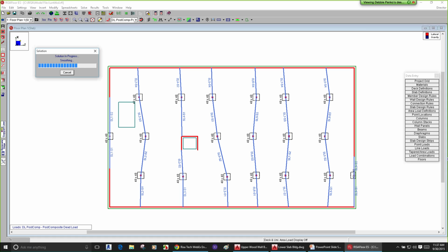Formwork, things like that, whether that makes sense to you. Maybe you just bump it to a 14.5-inch slab. Maybe that would help you because we were pretty close on punching shear. And then maybe go column by column, adding shear caps where you need them explicitly as you increase the slab thickness. But a lot of these things are design questions. You'd say, hey, does it make more sense to you as the contractor says to you, that's too much money for me to do one-offs.